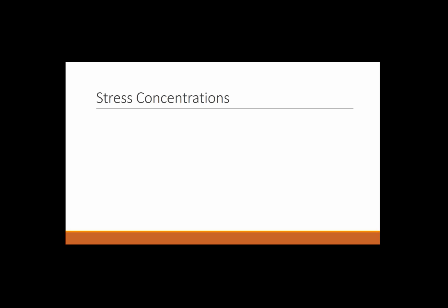One of these tools, which is helpful, is being able to calculate stress concentrations. So I told you that to get the stress distribution at that end, you would need to do, say, some finite element modeling. Well, there are certain geometries that people have studied and created equations for, where, without knowing the whole stress distribution, we can get what the maximum stress value is for that geometry.